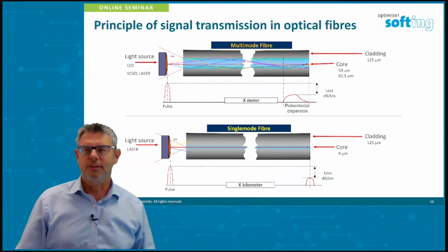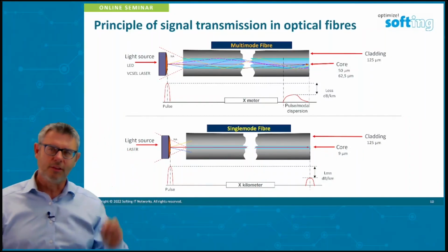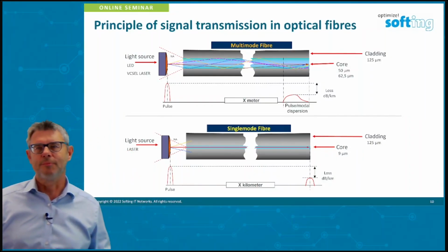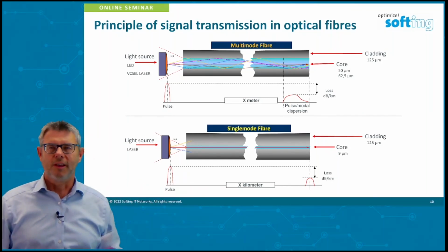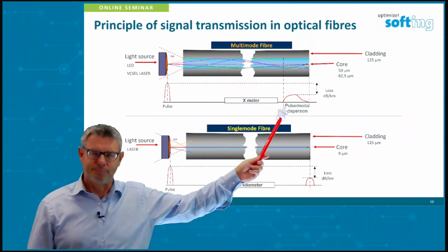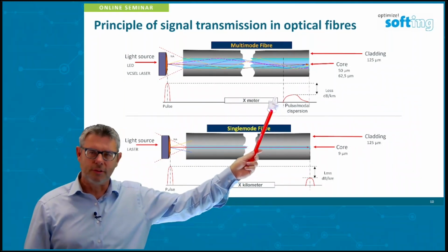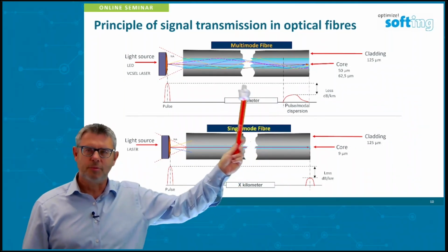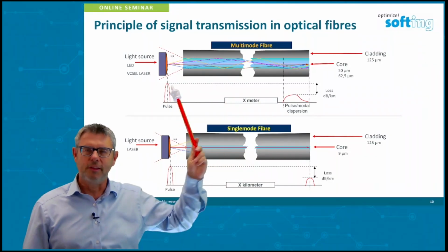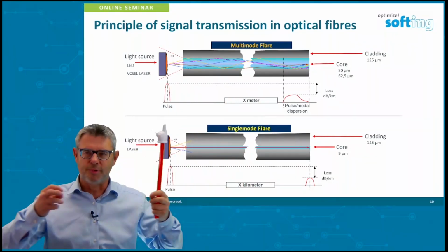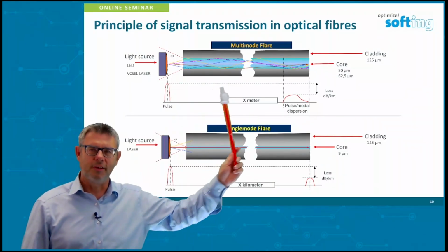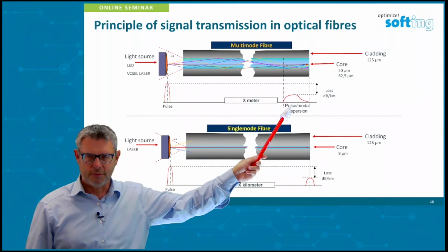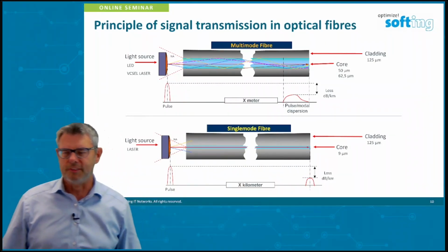So we got a series of modes in this cable, and unfortunately, through the ways they are going through the cable, we got this effect, what you can see here. It's a modal dispersion. So you see that the pulse, which was very sharp when you just send it in, now is spread out. And since the energy has to stay the same as sent out, it also gets down in amplitude. And this is the limitation for a multi-mode cable.